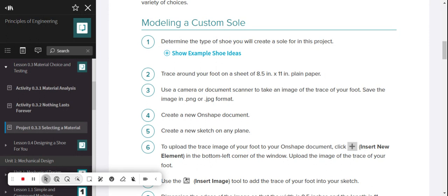To do that, you come over on the right hand side. You select this scale here on the right hand side, and then you click on the part, which is the only part you have here, and it gives you that value. It pops up an error because we haven't selected a material, and since we don't have a material, we can't find the mass or the centroid or any of those values, but we can still figure out the volume, which is what we're looking for on this segment of the assignment.